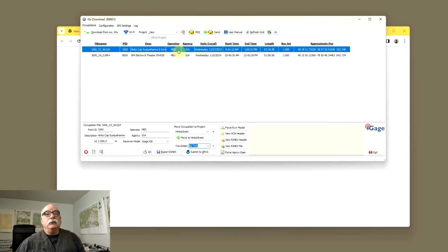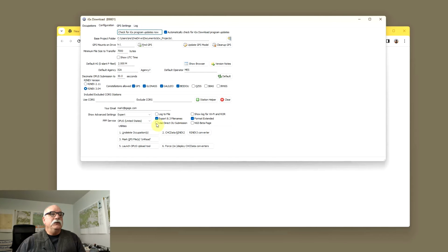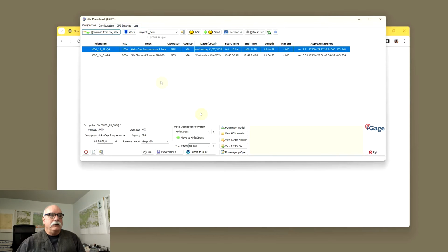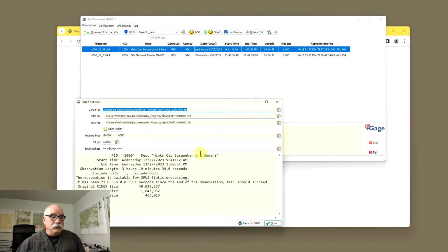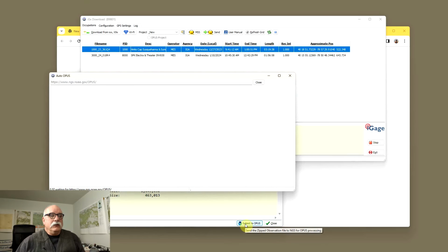Let's take this job and submit it to OPUS right now. I'll show you we've got direct OPUS submission unchecked, and we've got the beta page unchecked. So when I click submit to OPUS, it's going to prepare the file, which is decimation, and it's going to also zip it. So it's taken a 50 megabyte file and zipped it down to half a megabyte. We do that because there's no reason not to, and it's going to transmit to the NGS faster. So then you click on Submit to OPUS.